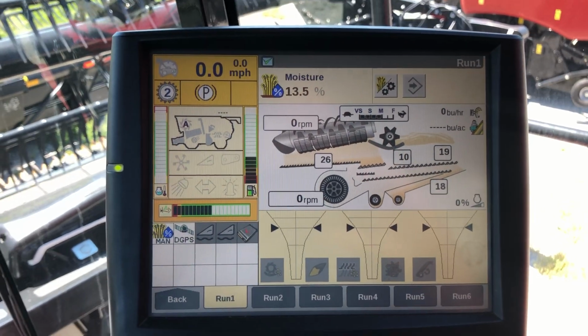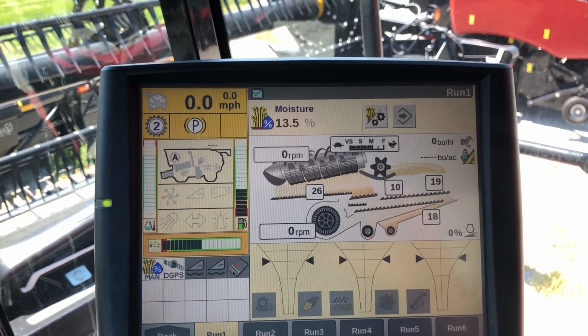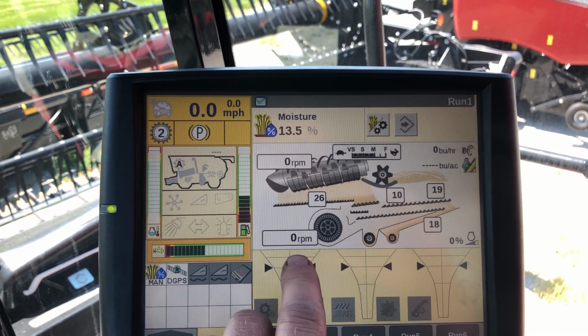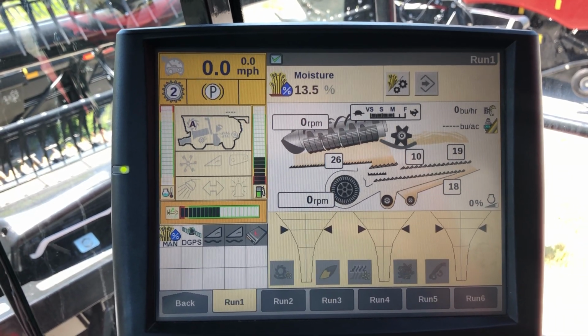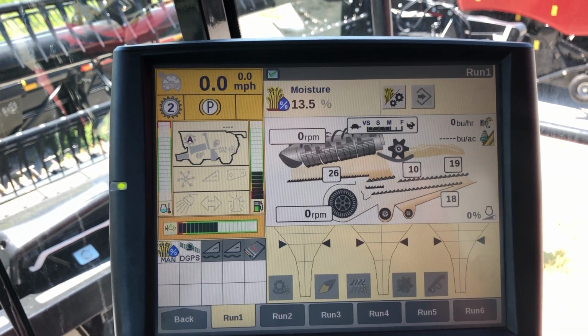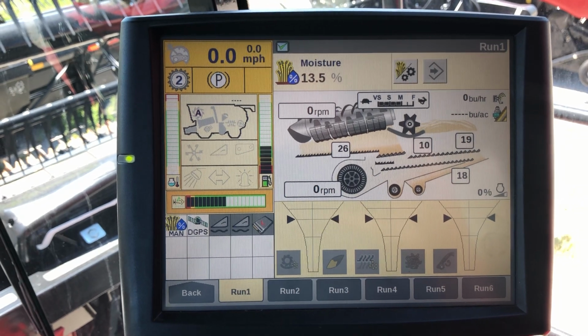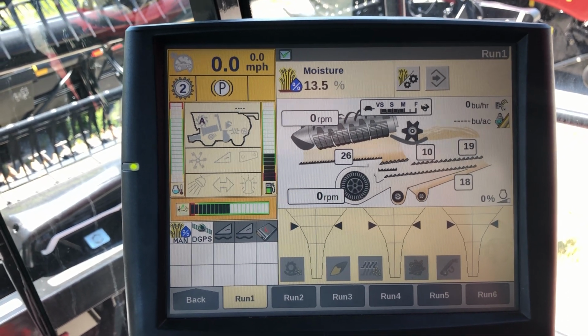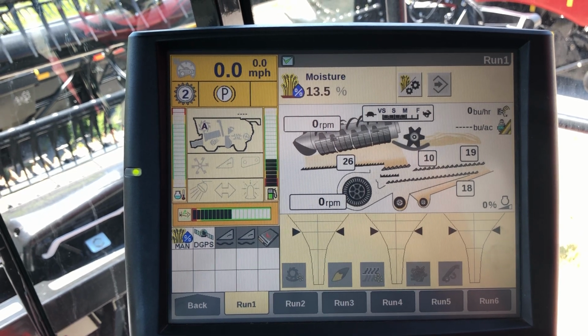is you'll have your fan set at a certain RPM, whether you're using manual settings or automation. Let's say we've got our fan at 1,000 RPM, and when we're on flat ground, that fan's actually running above that setting. So it might be running up around 1,100 RPM, and then when we go downhill, that fan speed really goes up high. The reason for that is that inclination sensor is not calibrated correctly to get the auto fan to work properly.